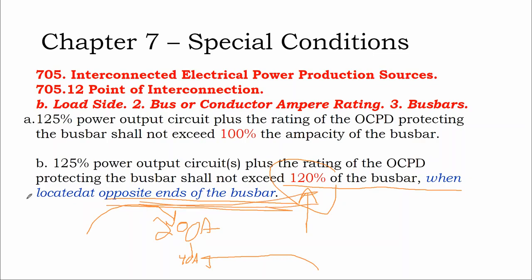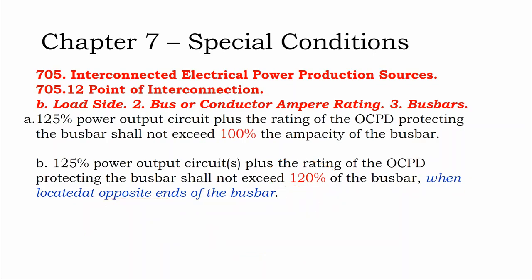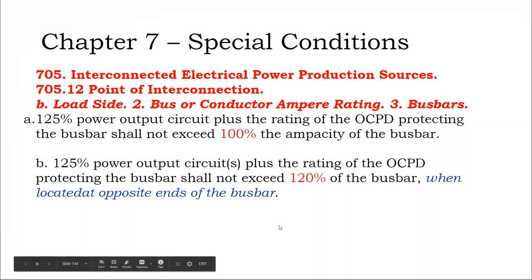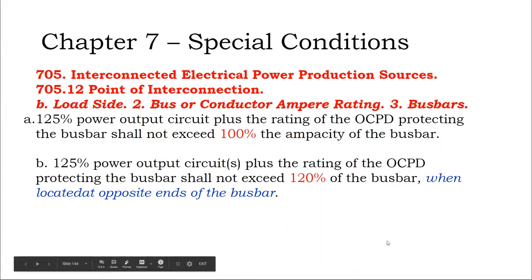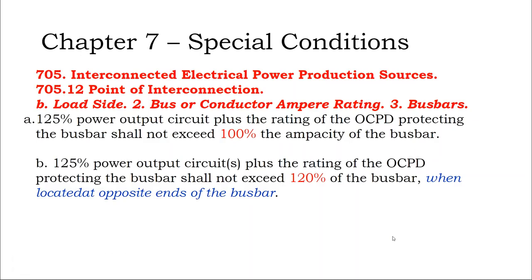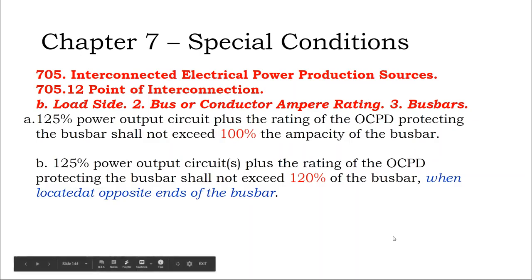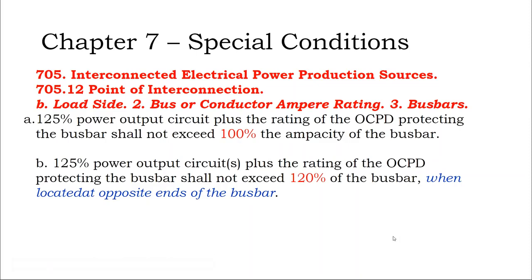So it's very common on solar arrays that are 40 amps or down, just to land them on the bottom of the electric service panel. Although not in all circumstances. In some cases, supply side connections are easier. In other cases, load side connections are easier. I personally think you have to think about your disconnect switch locations, and at which point one can be better than the other.